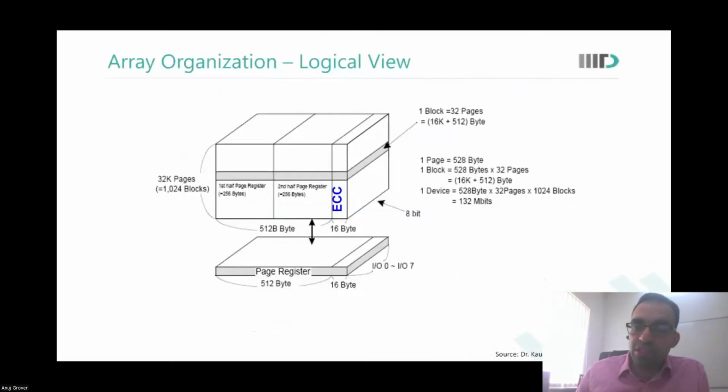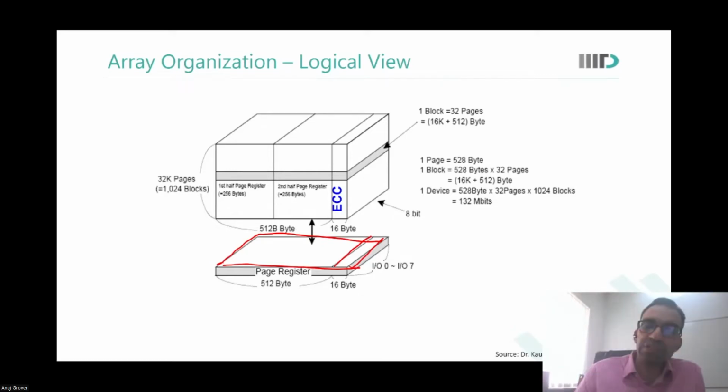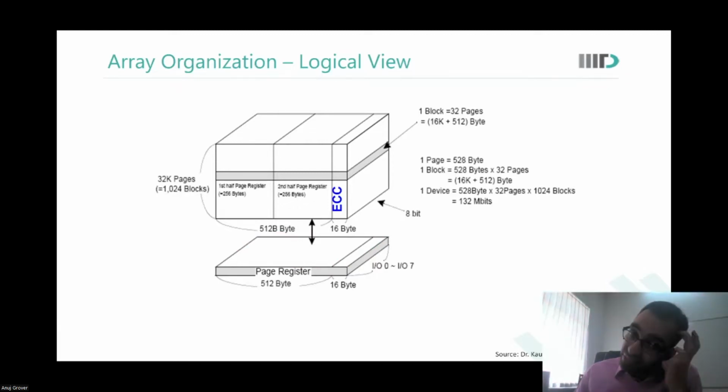And below the sense amplifiers, you have what is called a page register, which is a memory, which again includes ECC. It's a memory with ECC. This ensures decoupling of the speed of the flash from the speed of the processor or the processing system altogether, because the burst mode and everything can actually be implemented in this page register itself.